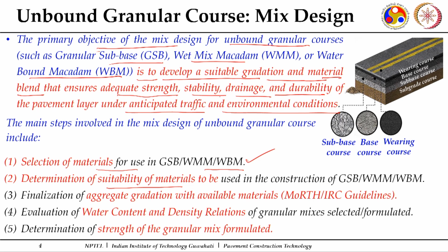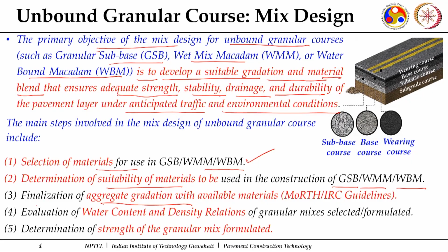Here we are talking about the unbound courses. So, whether that material, especially the aggregates, are suitable for use as a granular sub-base course, wet mix macadam or a water-bound macadam. Then, as I said, because you need to target a gradation, to achieve that gradation you may have to combine 2-3 stockpiles of different sizes of aggregates. So, this blending of aggregates also forms an important part of this mix design exercise, and this needs to be carried out as per the requirements of the gradations stated by MORTH or IRC guidelines.